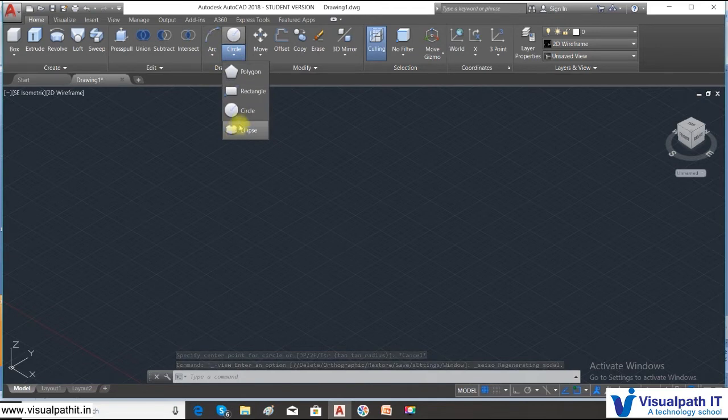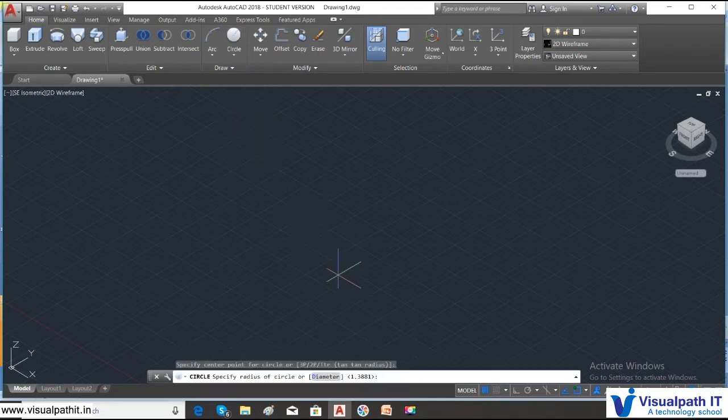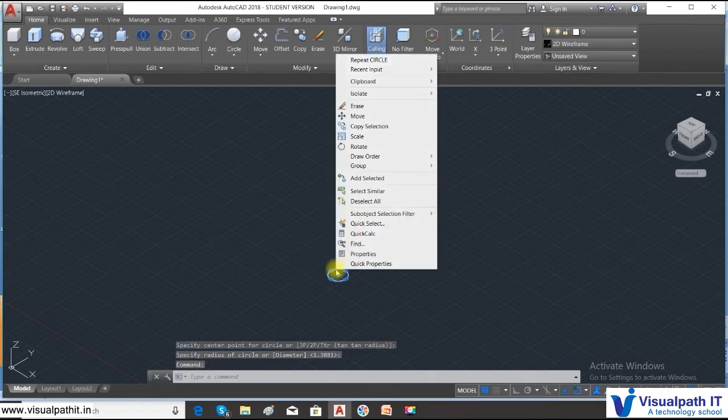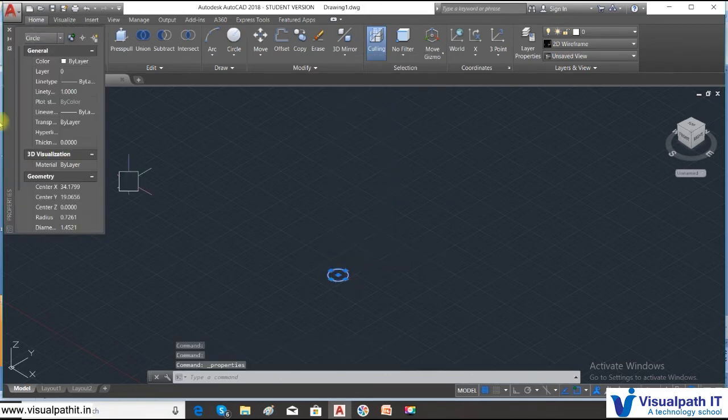So with the thickness command, what all you can do is radius of the pencil is 1.3 something. Select the object. Go to the properties, give the thickness, the length of the pencil that you want. You can even change the radius here.